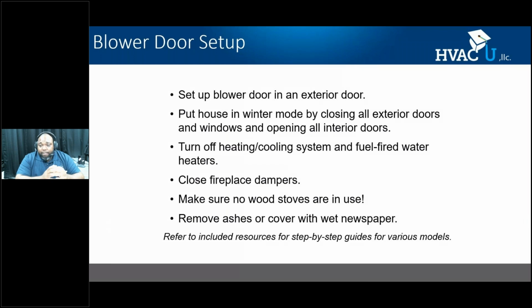If you have a fireplace, you're going to close that damper. You're going to make sure no wood stoves are in use. And if there was an active fireplace, it's a really good idea to put that fire out, let it cool, and then maybe put wet newspaper over the embers so that those embers are not pulled in when you conduct the blower door test.